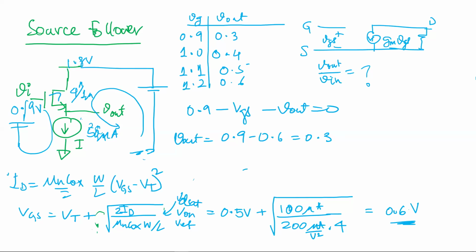Should be 1 for small signal, because if I change this by delta V, this changes by the same amount, delta V, and it should be positive. If you're getting another number, like RDS times GM, you go back here and see if something doesn't make sense, or you have to fix this one. You got what I'm saying, right?